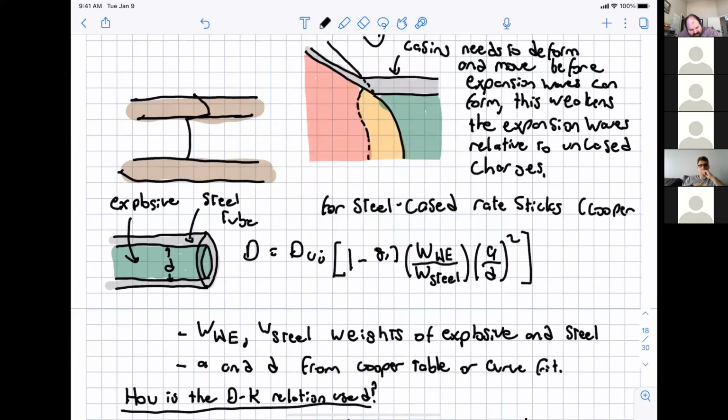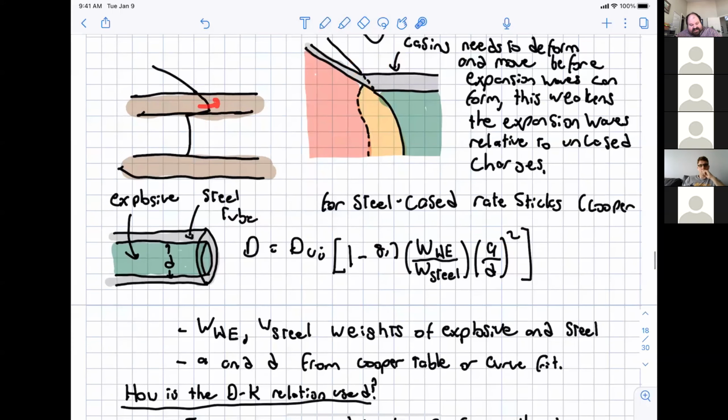Then it'll be transmitted like that. And so the shock will actually be detached and run in front of the detonation. It's really weird how that happens, but it does. And so basically, all of this correlation here is taking into consideration the details of how the shock of the detonation interacts and then propagates into the casing material. And that's very, very material dependent.